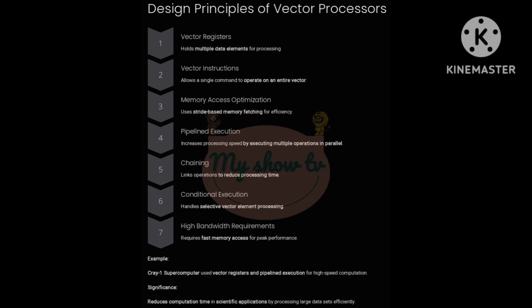3. Memory access optimization uses stride-based memory fetching, which efficiently loads consecutive elements in memory. 4. Pipelined execution, similar to CPU instruction pipelining, but here, multiple vector operations run in parallel to boost throughput. 5. Chaining allows dependent vector instructions to overlap their execution, reducing delays and improving efficiency. 6. Conditional execution selectively applies vector operations to specific data points, improving flexibility.